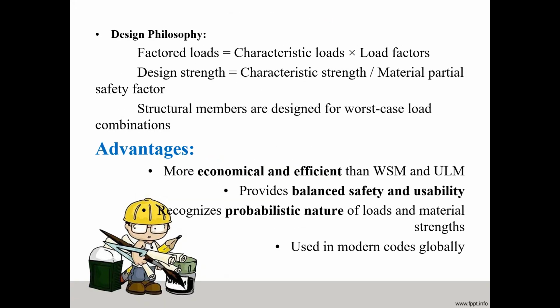Design philosophy of limit state methods: first one is factored load. The factored load is equal to characteristic load times load factor. Then design strength is equal to characteristic strength divided by material partial safety factor. Then structural members are designed for worst case load combination.